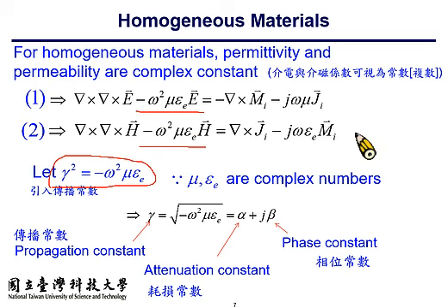On the right-hand side is the source. You have magnetic impressed current and electrical impressed current, and in the two equations, they work differently. In the first equation, for the electrical field, the source for the production of electrical field is the spatial variation in magnetic current and the time domain variation in electrical current.